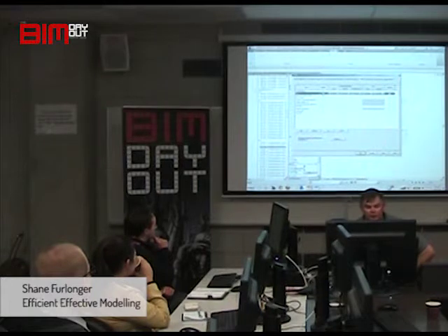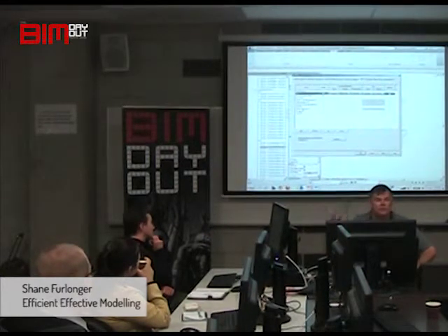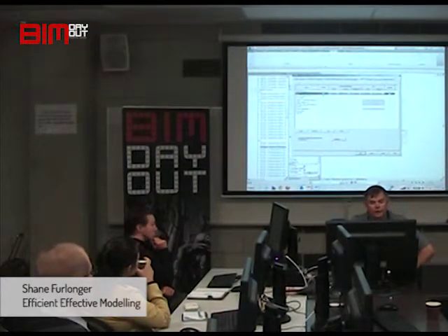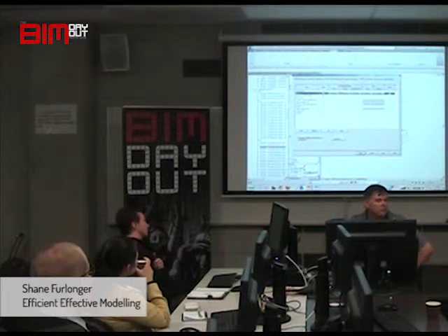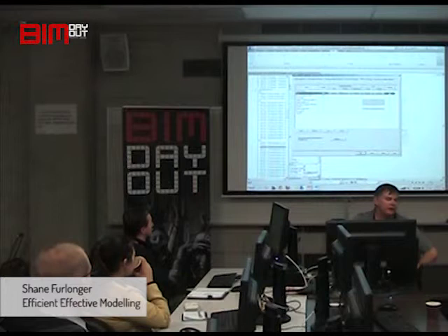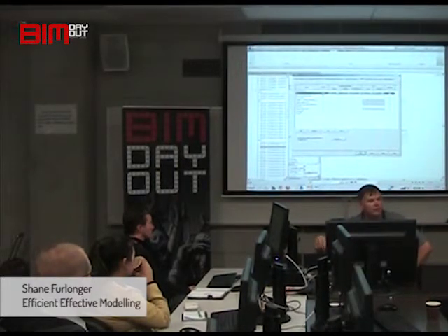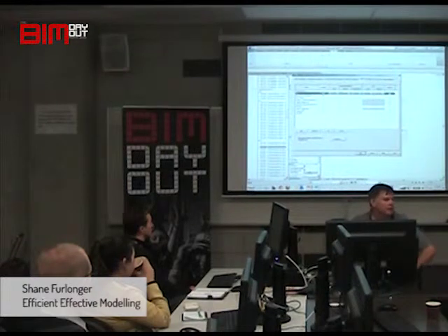The useful thing about them is, let's say you want to create a fire strategy plan, and you wanted all your firewalls to turn up red. So you could go in there, and say you know that you've got firewall as part of your comments or a fire rating on your wall. You can then say, if the rating contains 120, it's going to be red. If it contains dash 120, 30, then it's going to be blue. And if it contains whatever, it can be a different colour.